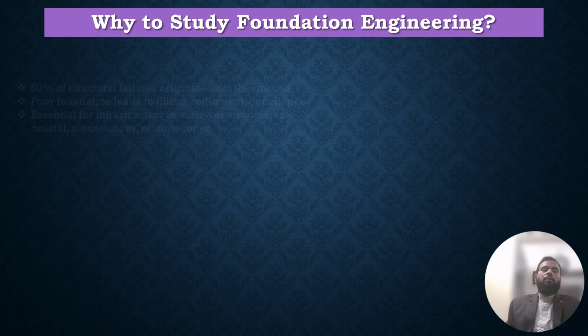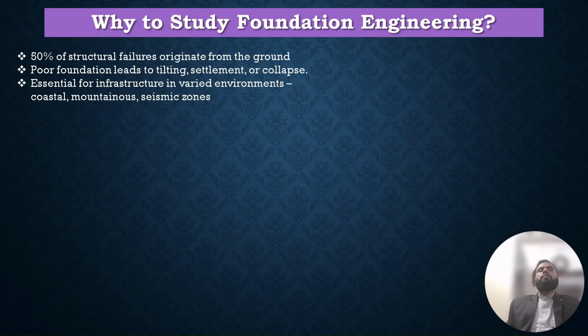So why study foundation engineering? Foundation engineering is an important subject. I already told that 15% of structure failures originate from the ground. If we don't understand the ground behavior or soil behavior in different conditions, then our structure will always be at risk. And poor foundation leads to tilting, settlement, or even collapse.